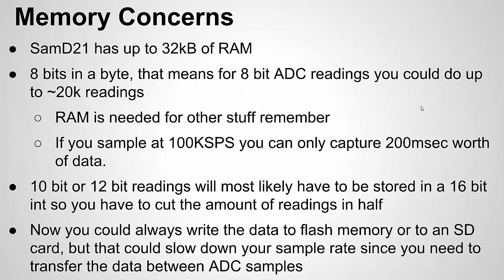Okay, let's talk a little bit about the memory concerns, more importantly RAM. So in the microcontroller, when our program's running, RAM is what's being used to store variables, local variables, add them to the stack, pop them off the stack. So RAM is basically our working space for memory. It also has flash memory that we can access, and you could always store stuff in an SD card or something like that, but then there's timing you have to worry about.